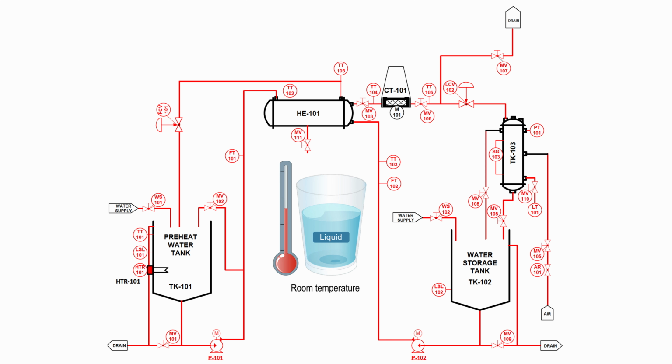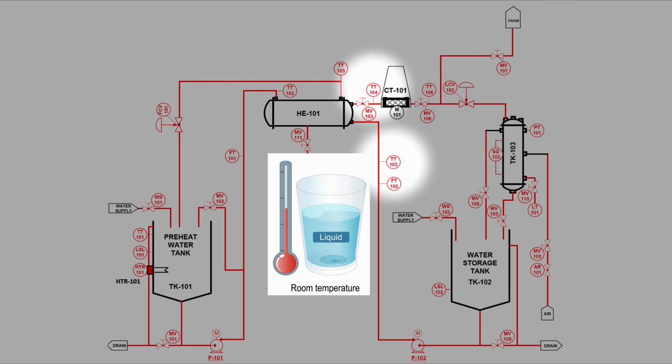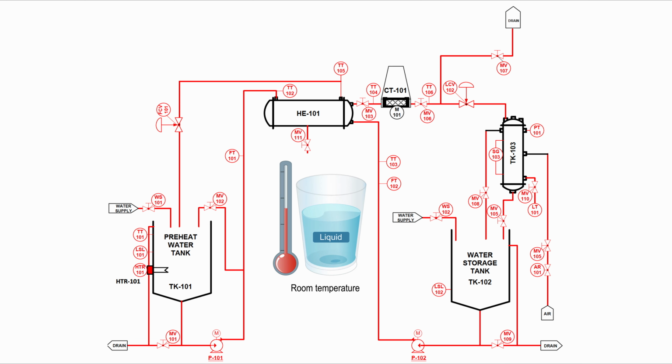And at this time, the readings of TT103 and TT104 could be almost identical, because there is no heat transfer process happening in the heat exchanger.